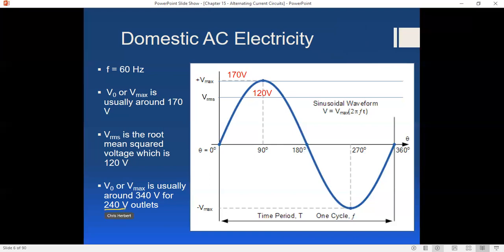That's the RMS voltage. The maximum voltage there is actually 340 volts. So in reality, alternating current actually sends a higher voltage at peaks than the actual rated voltage, because the rated voltage is really the RMS voltage.